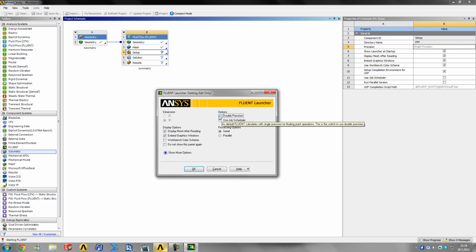Next thing to choose is single precision or double. Single is obviously when this is unticked. This one you need to choose for yourself and basically test, but single precision will go down to about 8 decimal places, and double precision will go down to 16 decimal places.